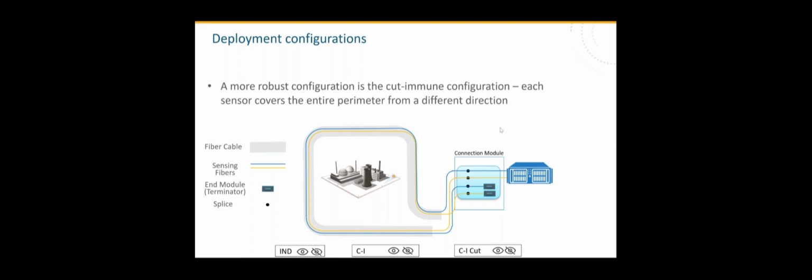And you said there is some possibility of integration with Honeywell. Which Honeywell products can be integrated, and which way? Is it a software or hardware integration? So any of them can be. The integration that exists today is for Honeywell EBI, Electronic Building Integrator. Others certainly can be done through an SDK level integration. I would love to see that happen. And there's always the fallback with hardware. Hardware integration is possible with almost any imaginable system, but that takes extra hardware, so it's not advantageous. So an SDK software integration to any package, Honeywell or otherwise, is possible.